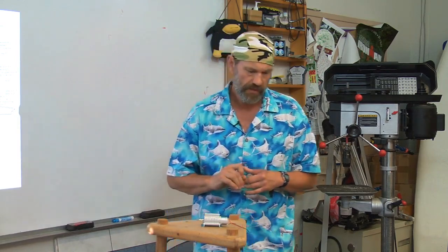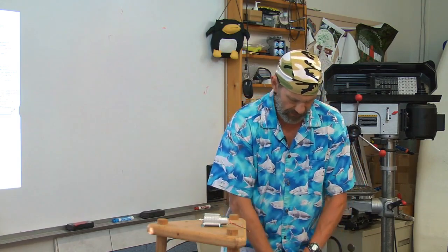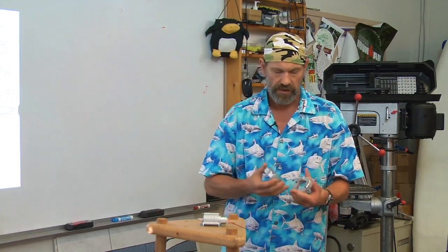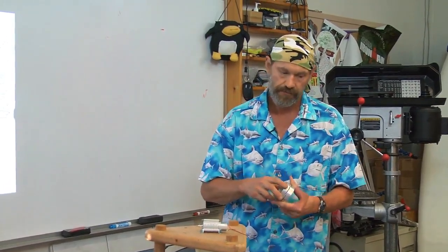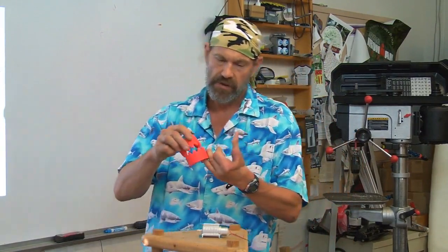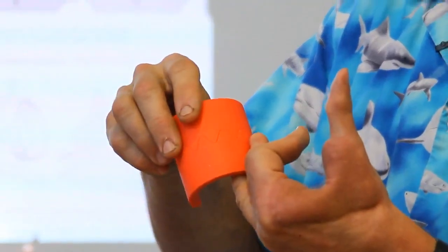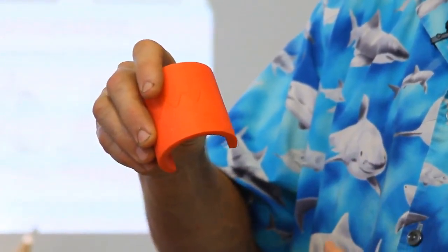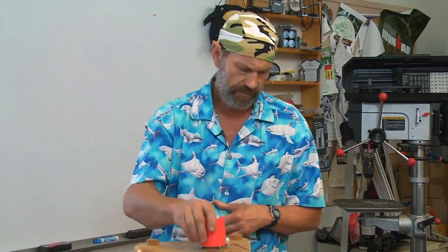Elastic averaging. Recall from topic 3 that we talked about kinematic systems and elastically averaged systems. Now we want to go into a little more detail on elastically averaged systems with respect to coupling design. We showed the kinematic systems earlier, for example the three-tooth systems, and one of the last areas we talked about was elastic deformation of these objects. By going to a lot of teeth, you have more of an averaging effect, so the error in any one tooth is not felt so much because you have a lot of teeth.